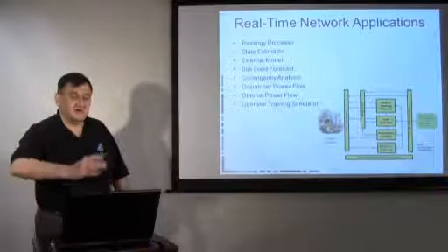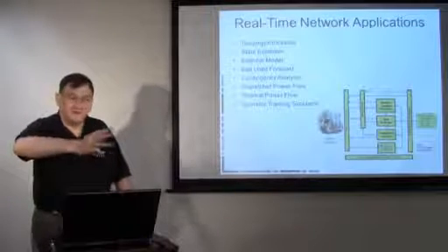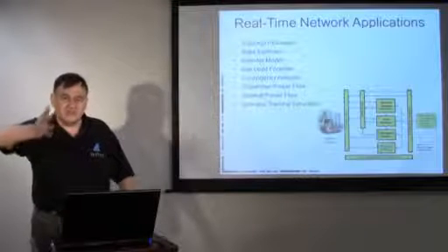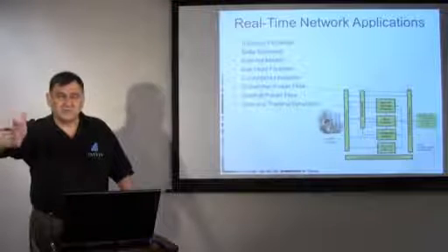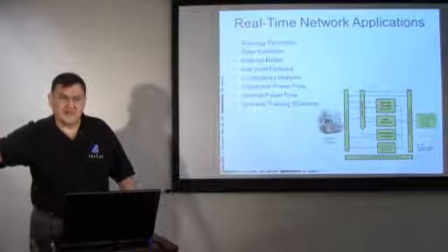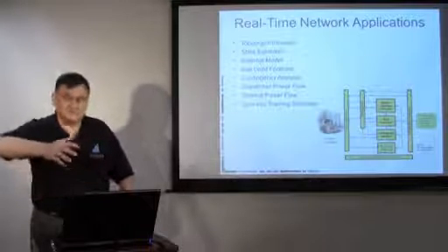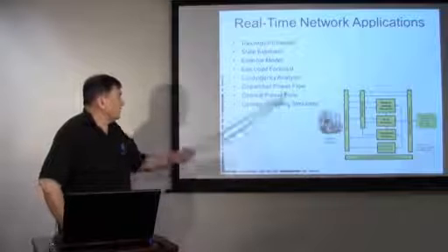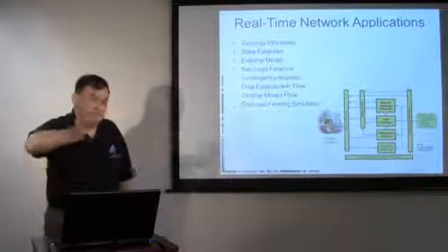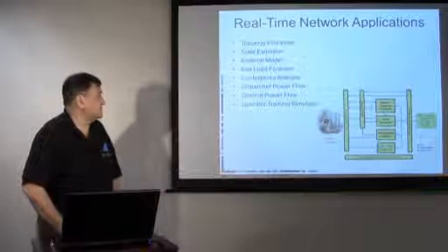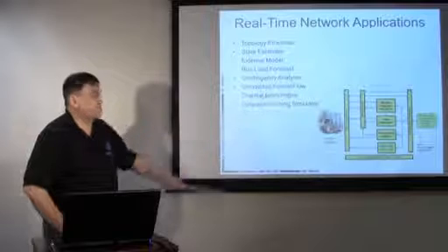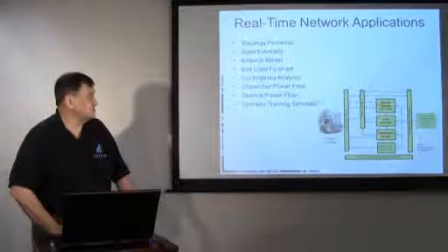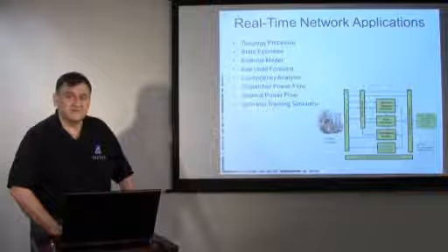The bus load forecast is looking at when you're doing your operations study. It's nice to say, well, the buses at 10 o'clock tomorrow are basically going to be at all these values, so you actually can forecast the individual loads on buses, not just your system load. You have your contingency analysis, running all the different outages, telling you what's overloaded. Your dispatcher power flow is where you as the operator can make your own custom studies to set up the system in a different configuration.